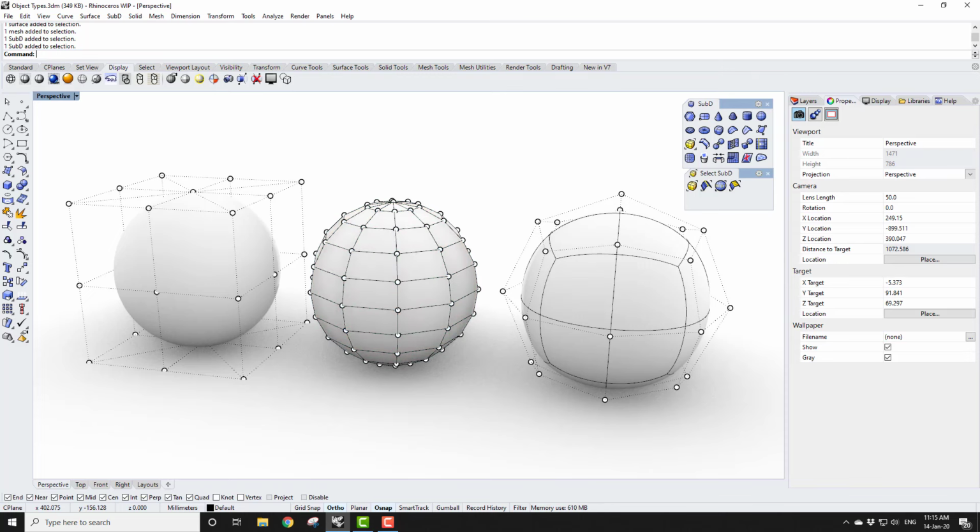If you've been a Rhino user for some time, then you may be familiar with plugins such as T-splines and Clayoo. These brought a SubD workflow to Rhino, but crucially these were mesh-based. So the underlying geometry was a mesh which was smoothed to approximate a curvature continuous surface or polysurface.